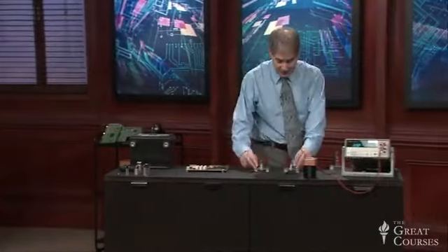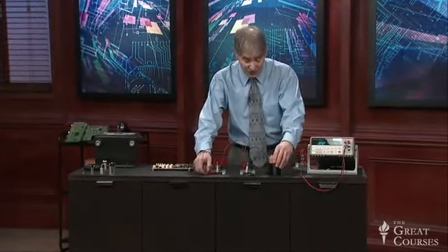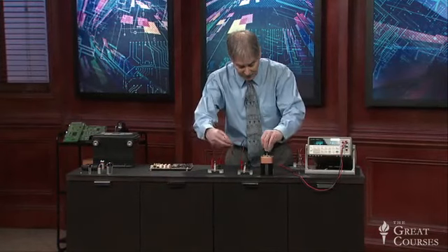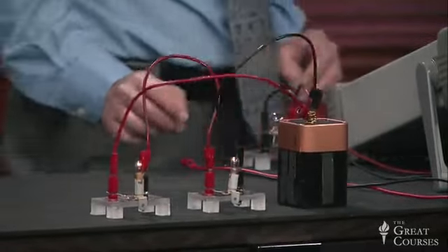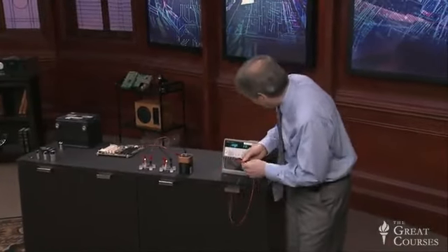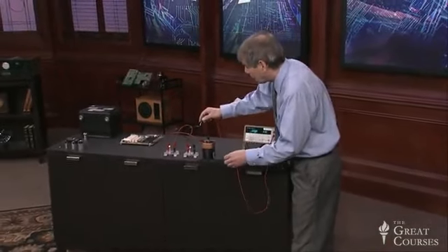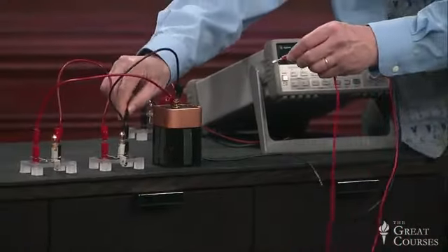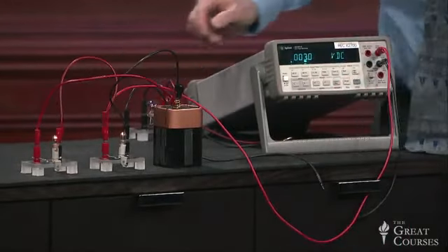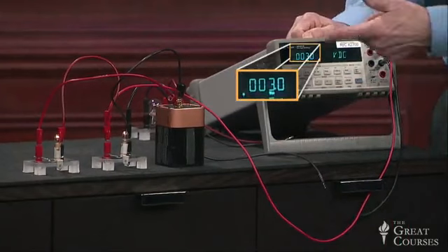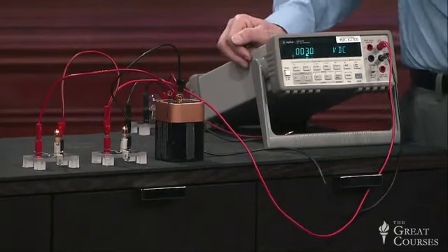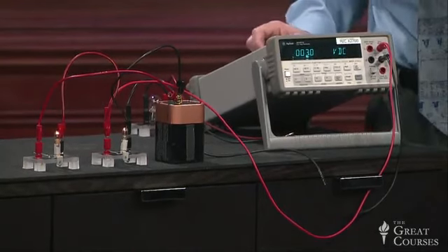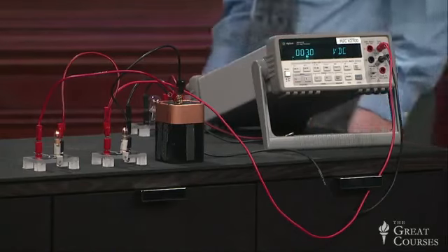Okay, I have an example of a voltage divider over here. Here is a circuit consisting of a couple of resistors. Well, are they resistors? Yes, they're light bulbs, and incandescent light bulbs are just resistors. And I'm going to connect it across this 6-volt battery. I'm going to come around and get my voltmeter fired up, set to read DC voltage, and I'm going to read the voltage across this second light bulb, and you can see it's just about 3 volts. We're across a 6-volt battery, and we have two identical resistors. They happen to be light bulbs, and consequently, we are good with 3 volts. We've seen that the voltage divider is working. So there's an example of a voltage divider.